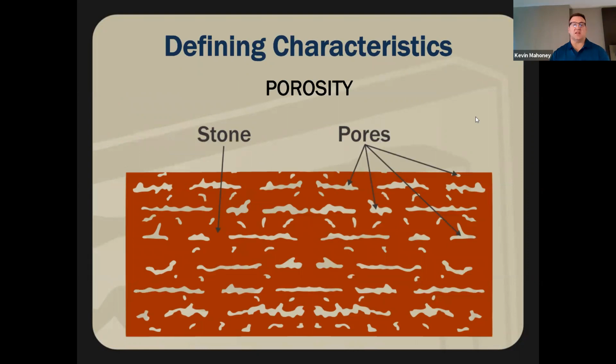Think of this as a cubic foot of limestone, and it has pores that absorb water. And when water gets in there, especially in a freeze-thaw climate, it can expand, contract, it can blow apart the stone, it can rupture the stone. So the denser the stone, a lot of times the more durable the stone. That doesn't necessarily mean that a dense stone is the most abrasion resistant stone or the most chemical resistant stone just because it's dense.